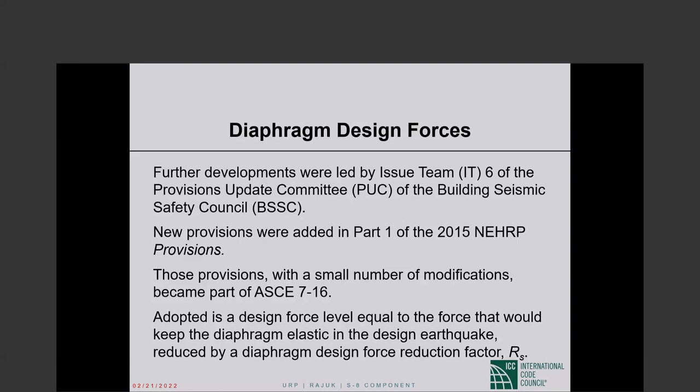That is true of the redundancy provisions. So it is not that I switched to AC 710 across the board, but for the building separation provisions, I definitely switched to AC 710. Diaphragm design force, AC 710 and AC 705 are the same if you are looking at section 12.10.1. So it doesn't matter whether I say 710 or 705.